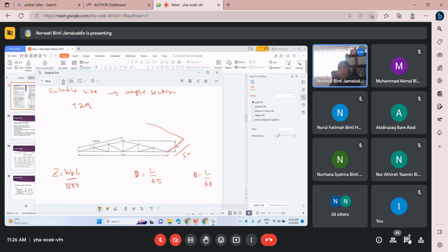So it's not logical for us to have just 5 meter. So we will have a few trusses here, and your purlin will still run until the end of the building. It will be like 20 meter long, but since it is actually a continuous member, for this case we need to consider only one span.